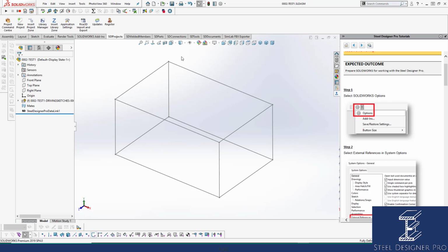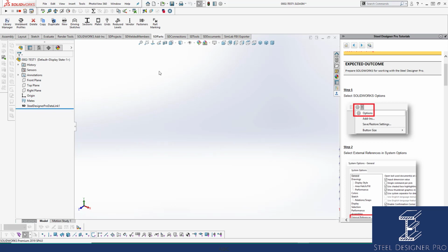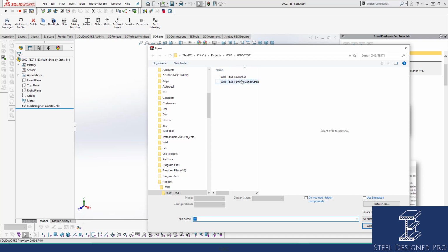At the moment, I'm currently residing in a zonal level assembly, and in there I have a driving sketch component. Driving sketch components can be added from scratch and then drawn in as we go. Driving sketches don't have a solid, so you cannot select it and delete it using our parts delete method. So I'm just going to delete it out so that it's gone completely. Hit Control Q, Control S, and then open up the folder and delete it from here, so it's gone.